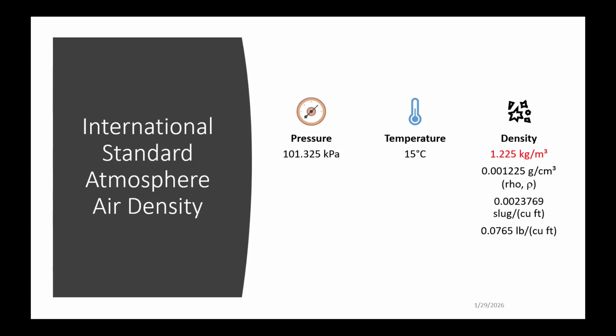Density altitude is the equivalent standard altitude for measured density. So at our airport, we sit at 7,000 feet above sea level, and it's not unusual for us to have the local AWOS report our density altitude at 9,500 or 9,700 feet. And all that's saying is that the density it's measuring at the field elevation is equivalent to what a standard atmosphere would be at 9,500 feet.